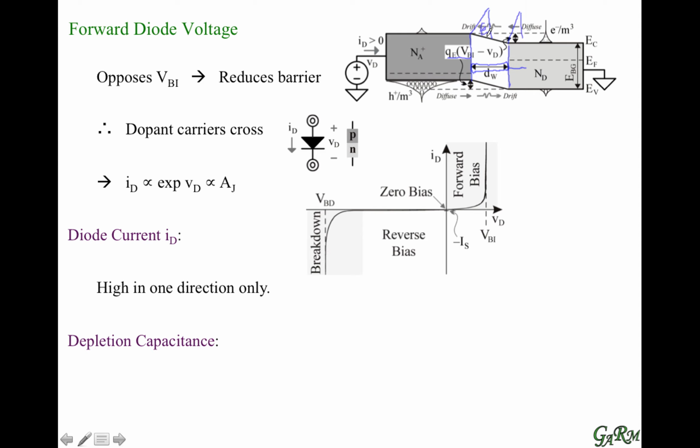First, the higher the cross-sectional area, the higher the capacitance. So that capacitance is going to be proportional to the junction area. But we also have the distance between the plates. If the distance is shorter, we have a more intense field and therefore higher capacitance. We can hold more charges. So when the distance is short, we have more charges, and as a result, capacitance is higher. That's why capacitance is inversely proportional to the separation of the plates. Now we also look at this voltage here.